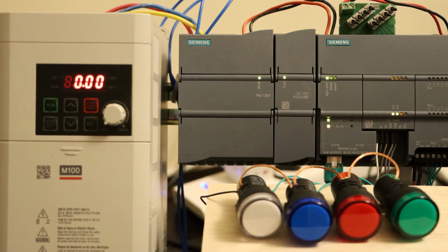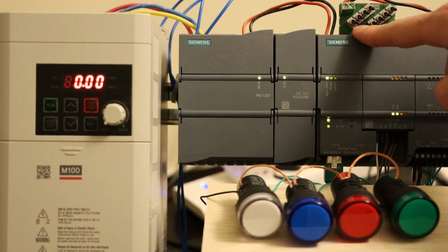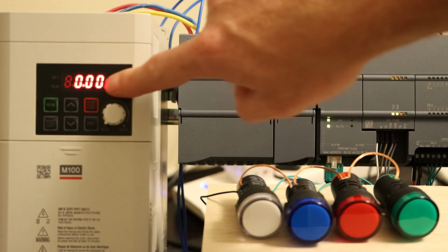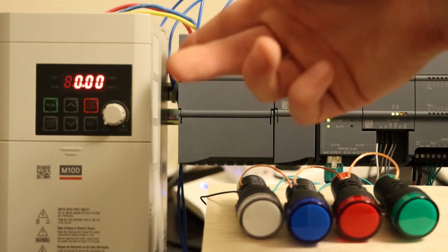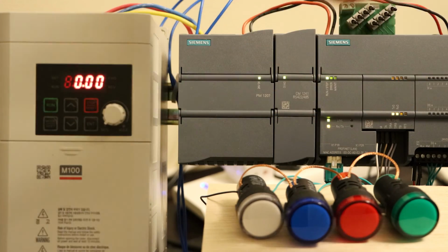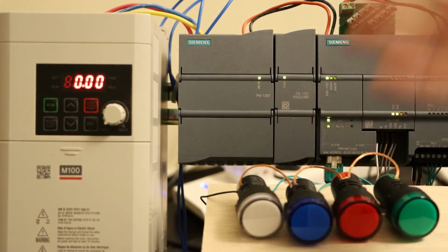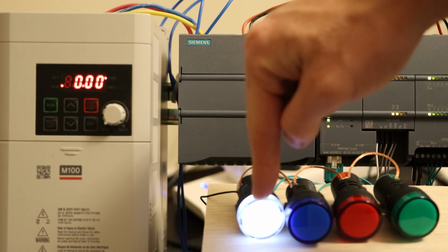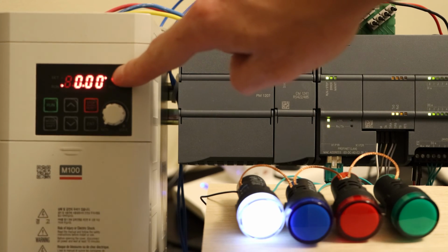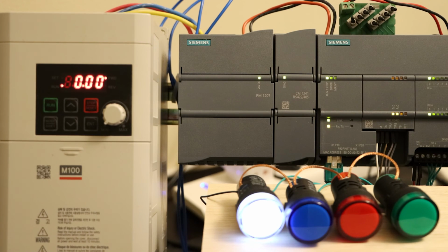Yep. But if we come to these switches, we should be able to start influencing stuff. So if we put it into run, we can see this, when it's not running, this VFD gives the hertz that it will run at when it does run, if that makes any sense. I'll just show you. So this is saying 0, so when I run it, it will run, but at 0 hertz. So we can see our run light is on, and our run indication LEDs are on, but it's at 0 hertz, so it's effectively doing nothing.